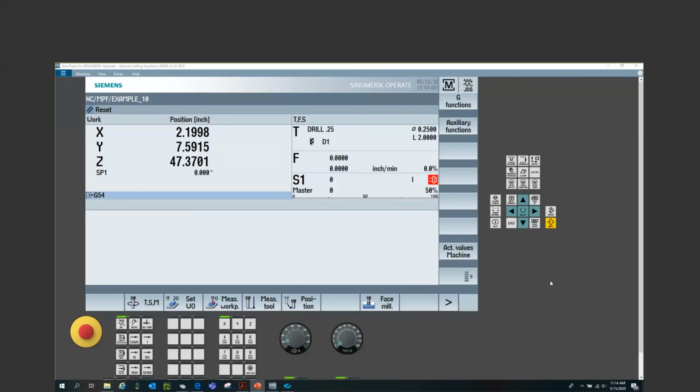Yeah, that is correct. And the reason why we do that is you do want to try to observe compatibility between your machine tool and the offline software, specifically when you're programming conversationally. So, if I write a program in 4.7, let's say, in conversational, it won't necessarily run in a 4.5 machine. So you always want to make sure you keep that compatible. 4.7, 4.8 are basically identical, so you don't run into it quite as often. But that's why we have the versions for sure. Great point, Chris. Thanks for bringing that up.